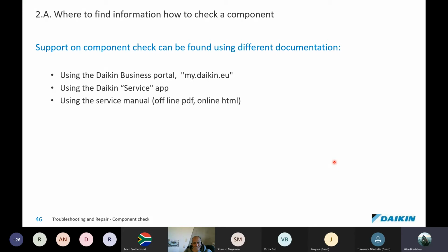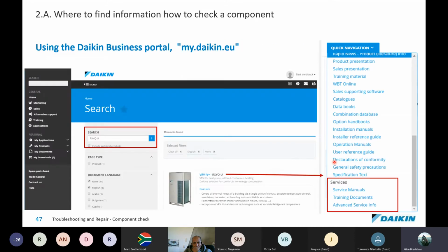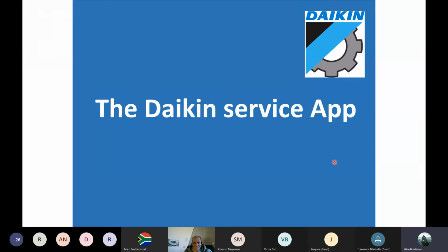It's also a useful thing in planning if you've already had a phone call where somebody says, oh, my controller's flashing an E3 alarm. You can get the manual out and say, oh, these might be the items that I might need to take with me, or I need to get my head around. This is how I'm going to tackle the problem when I get to site. All right, so we've gone over the manual.